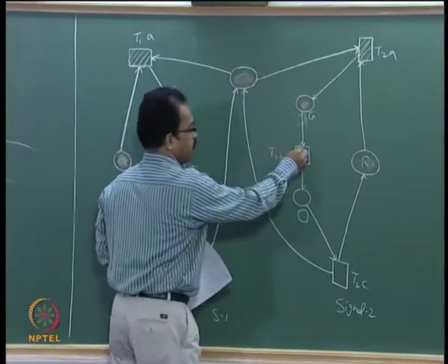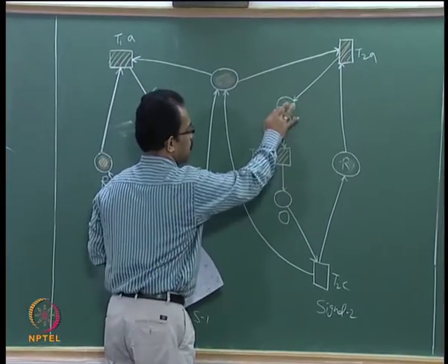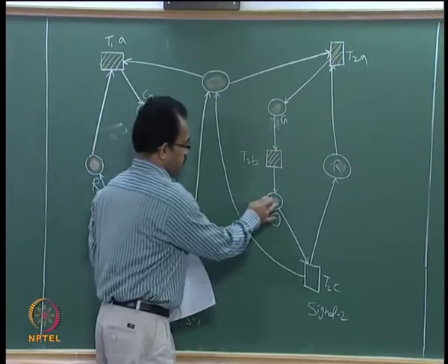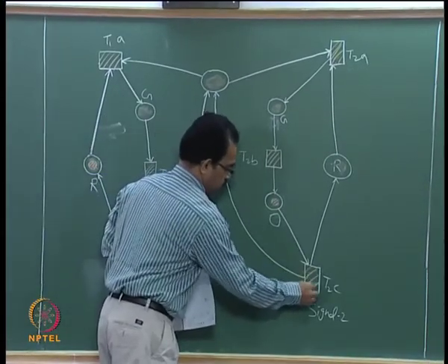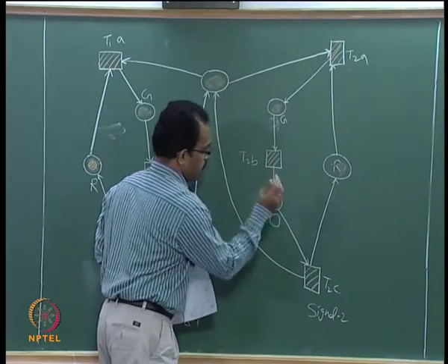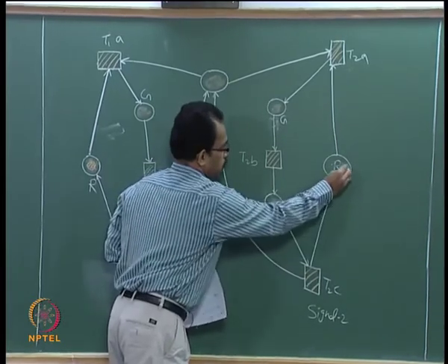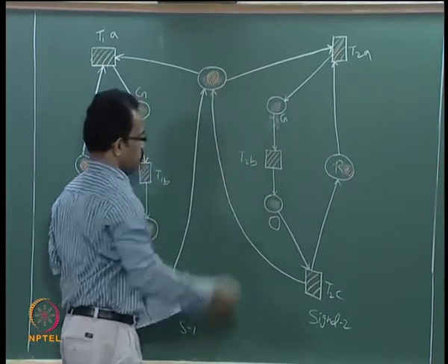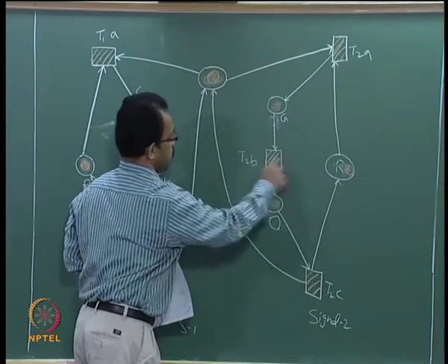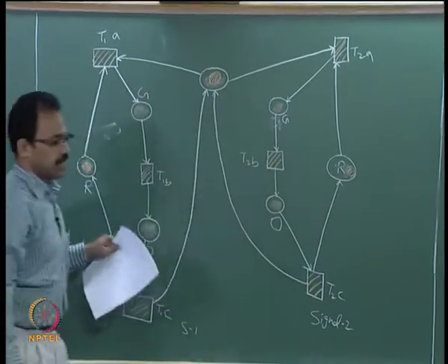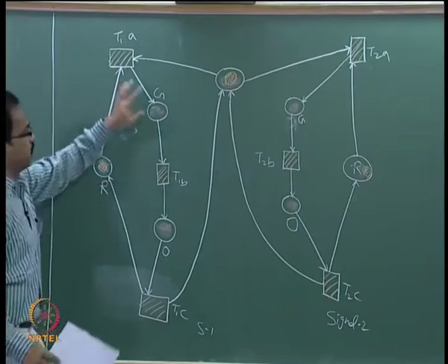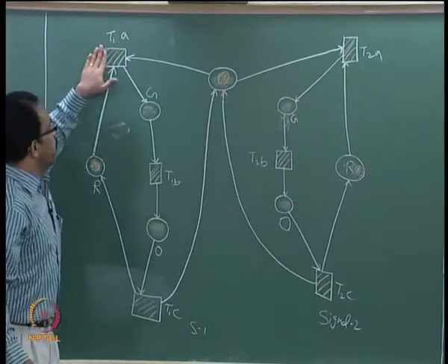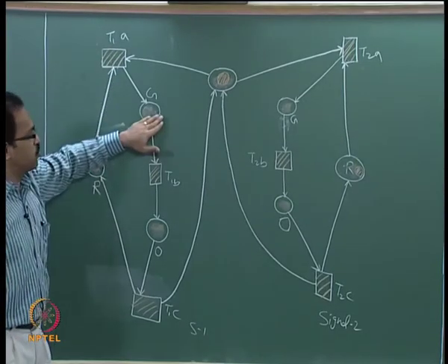So again the same way we will do the transition. So this transition, the token will be passed to this, and when you activate this transition, this token will be moved from here, it will go to here as well as to here. So when we activate this transition, you will be getting the token at here and here. Now both the signals are red, therefore we can have the next transition from here. So unless this token comes back from here, this cannot activate and this red signal cannot change to green.